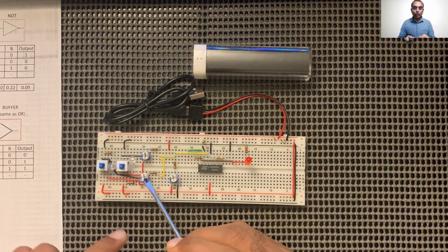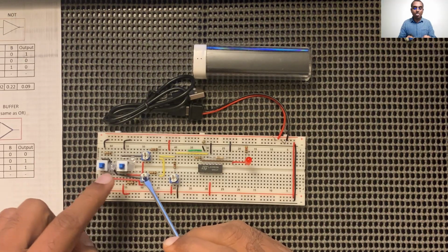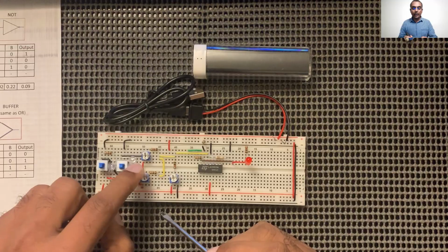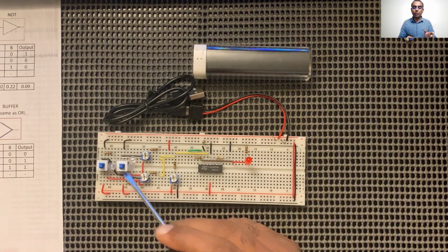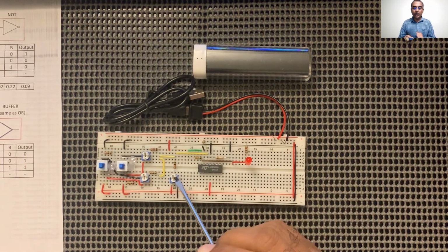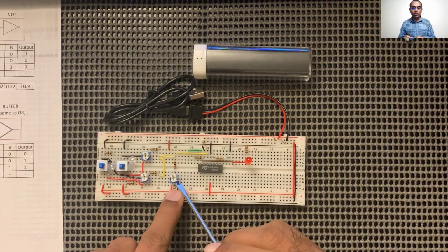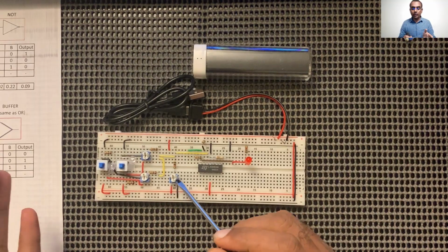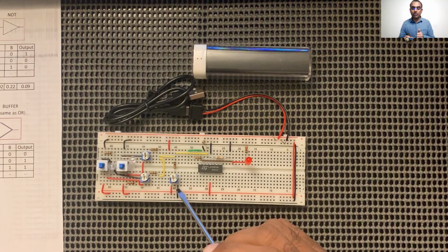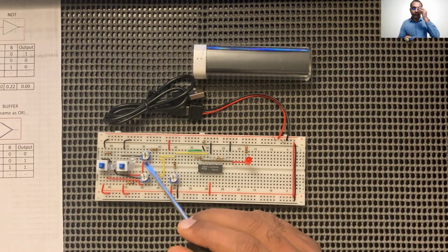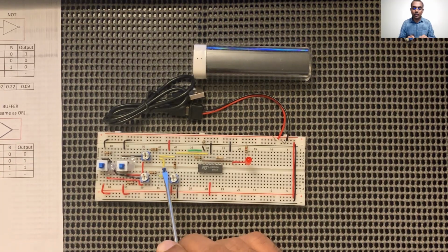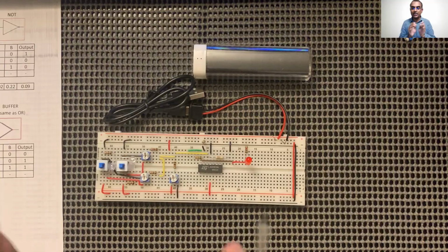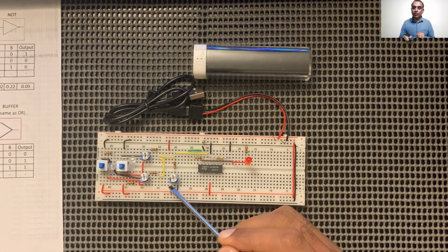So we have three potentiometers. The potentiometer that is closer to me is connected to switch A. So we will call this potentiometer A, and the one that is on top of potentiometer A is connected to the second switch, that is switch B. The third potentiometer, which does not have a connection from a switch and is connected directly to the power supply, is the bias, and it is always connected to the summation node. In fact, all three potentiometer wiper outputs are connected together through these yellow jumper wires. So that acts as the summation node, and each of these potentiometers is 10 kilo ohms.